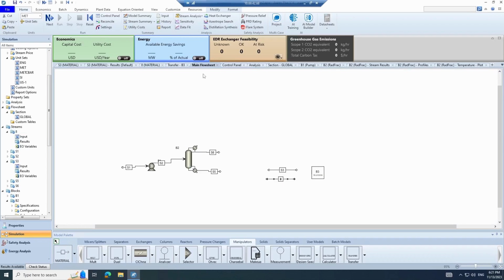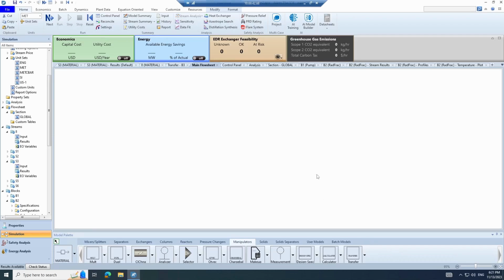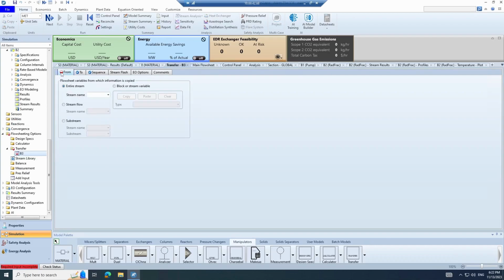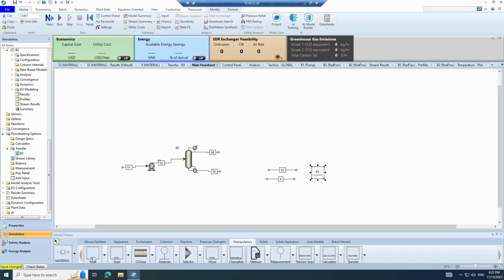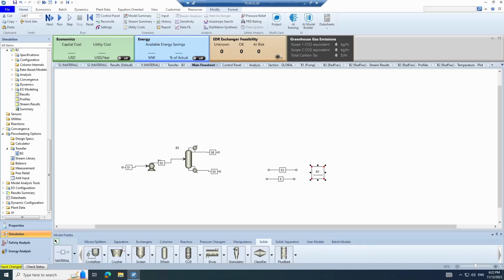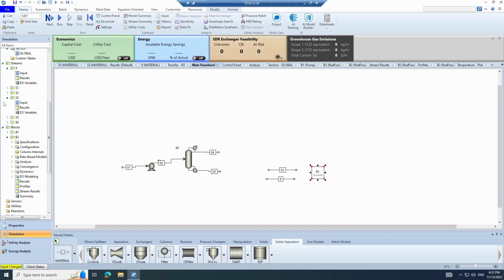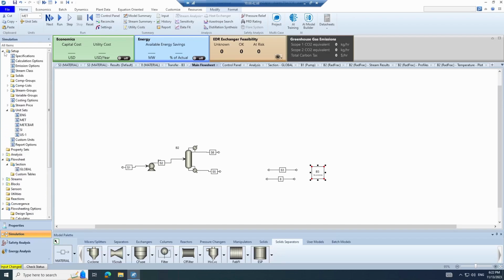And that's all of the unit operations I will be going into detail for these tutorials. All the other ones here are very straightforward, where if you have a value missing, it'll always tell you you are missing something based on the red circle, both here and it'll tell you here as well. So just looking over some of them, you have the multiplier one that will allow you to multiply streams. You have duplicating streams as well. For solids and solid separators, you have crushers, you have granulators as well. So different unit operations for solids. And for solid separation, you have different types of solid separation. You have solid gas separation, such as the cyclone. You have solid liquid separation, such as the centrifuge filters, or just regular filters as well. So each of these unit operations, you'll always know what you need to specify based on if you have any red circles on the side here, and you'll know that everything is specified once all of the circles disappear.